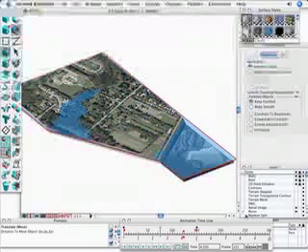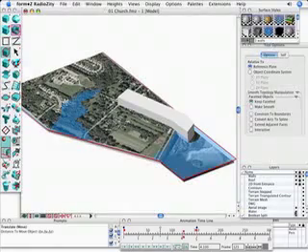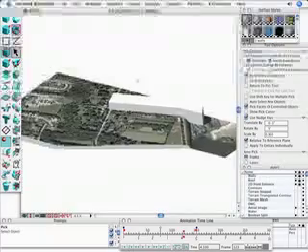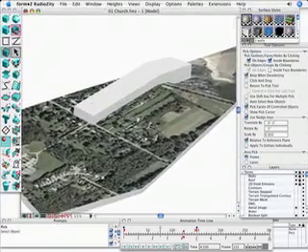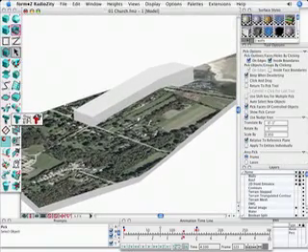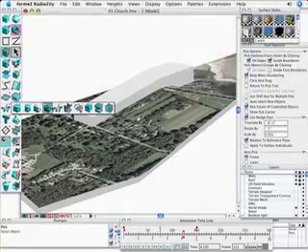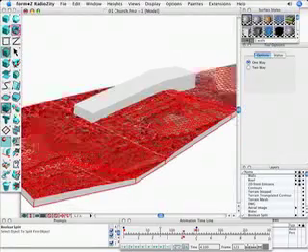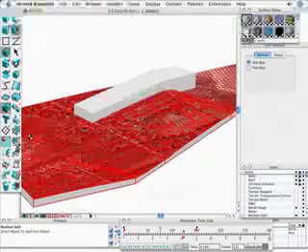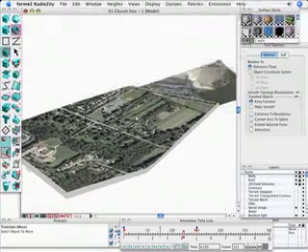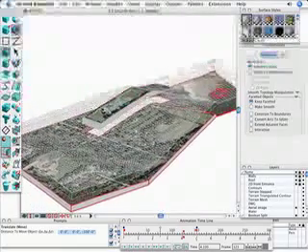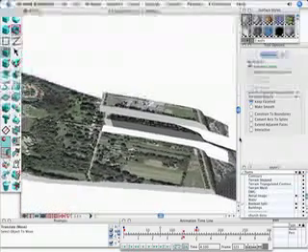And the other advantage of this being true solid geometry is, let's say we want to work on a smaller section of our site. We can just create a solid volume, which represents a smaller section of the site. And then using the Boolean tools, we can do a Boolean split. And then we just simply move this other section down so we can work with a smaller section of our 3D solid site plan as we build the rest of the buildings on our 3D model.